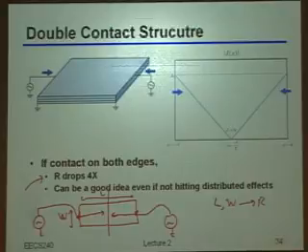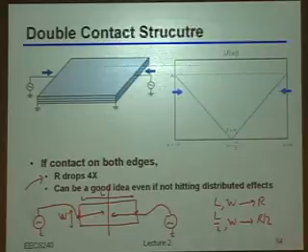Yeah, they're in parallel, right? I have 2 resistors, each of R over 2, in parallel, right? So by the way, all we said before was that effectively the length became half of the length. So that got us to R over 2. And then if we just put 2 of those resistors in parallel, which is indeed what we're doing, then now actually we have 1/4 of the resistance we originally had.